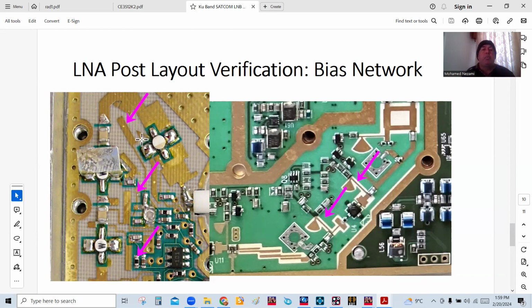And so somebody figured, well, can we put many of these stubs in parallel so that we can get a broader effective open stub at various frequencies within a certain band? And that's what this radial stub is, really. You can see that the distance from the point where it connects to the impedance line to the edge of the radial stub varies until you get to the middle, and it's symmetrical on that side too. So really, it's a bunch of planar distributed open stubs, and you end up with broader bandwidth. Okay.